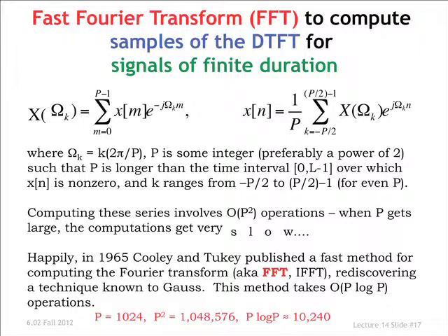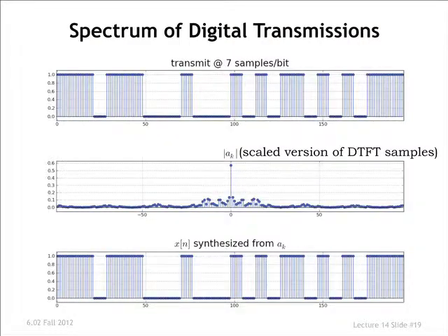That's developed in some detail in section 13.2, but we're bypassing that this term to keep the story simpler. So when you see these plots, you'll see a magnitude A of k, a symbol associated with the discrete time Fourier series. These are Fourier coefficients associated with the periodic replication of this signal outside. So it's a discrete time version of the Fourier series you may have seen in 18.03.